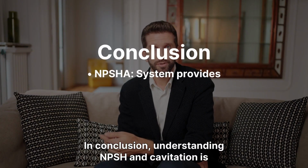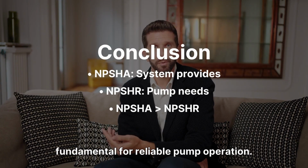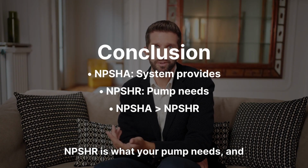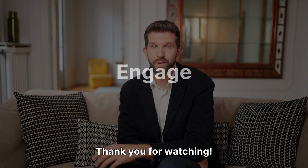In conclusion, understanding NPSH and cavitation is fundamental for reliable pump operation. Remember, NPSHA is what your system provides, NPSHR is what your pump needs, and NPSHA must always be greater than NPSHR.